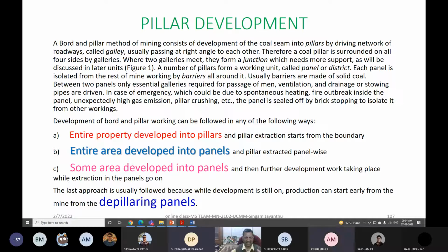And in general, when we are going to deeper and deeper horizons, elliptical is more stable than even circular when there is a biaxial or triaxial stress field of different magnitudes. That means in the vertical direction or in one direction, the stresses may be more, in another direction they may be less. In that case, instead of circular, even elliptical shape is more stable.